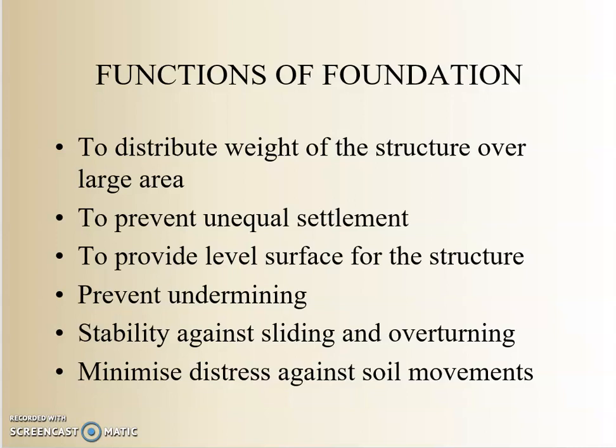Now, why do we provide foundations? So let's start from the fundamentals. First is distributing the load over a large area. Then, of course, to prevent differential settlements, to provide a level surface for the structure, to prevent undermining. Okay, then foundations are also provided in order to give stability against sliding and overturning, and to minimize distress against soil movements.